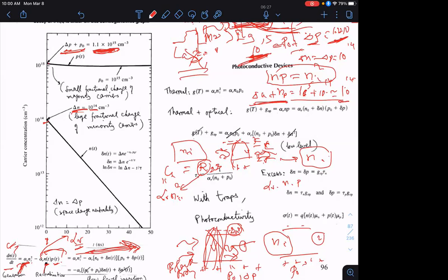All right. And now I move to the scenario where I'm actually shining laser light for a while, creating excess electrons and holes, and then turning off the light at time t equal to 0. And I want to see the rate at which these electron and hole carrier concentrations decay back to the equilibrium values. If we waited long enough, the hole concentration would decay to what? Can you repeat the question? If I waited for a long time, after I turned off the laser light, what would the hole concentration go down to? 0. Wouldn't there be no transfer once there's no?